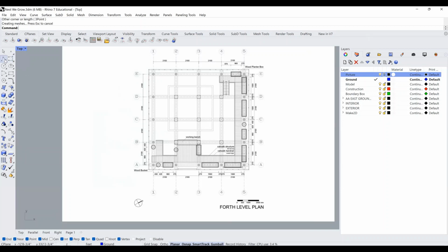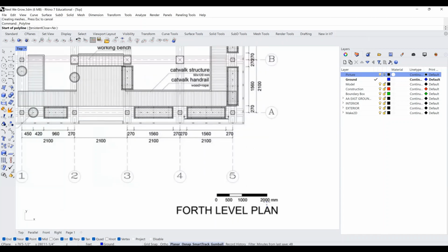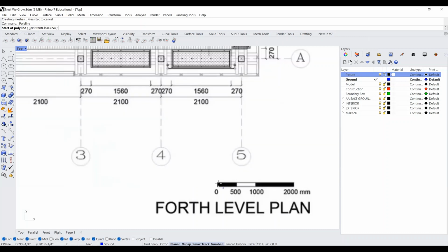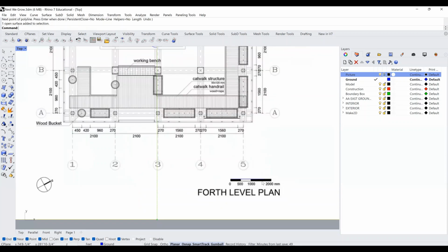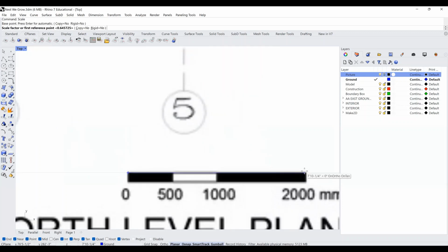We need to scale this accordingly. Just by doing several trial runs, I know that there are approximately 305 millimeters in a foot, so I can just insert that into Rhino itself as an equation. I will make a line as a reference from this end of the scale and type in 2000 divided by 305, comma 0. This is going to immediately give me that Cartesian coordinate in the x direction of what 2000 millimeters is in feet units.